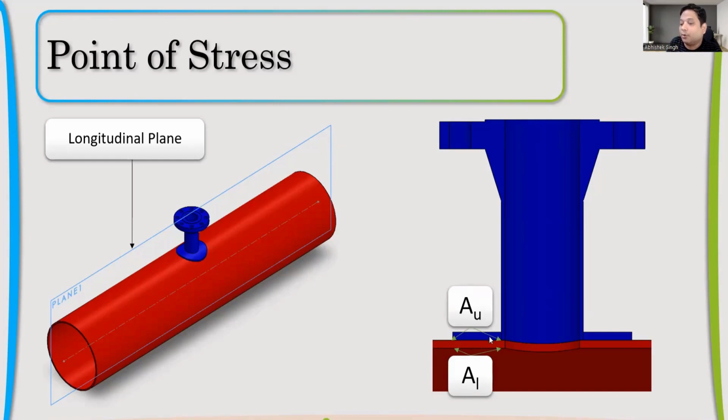What we are talking about is the stress at this point in the longitudinal ring. Can you see that arrow? At this point, and at this point. There will be an upper and lower point, because due to bending, there will be positive and negative stresses, right? For membrane, it does not matter.